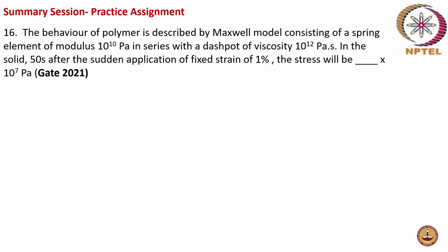Uh, stress will be constant when it's connected in series, so the strain will vary. They have said a fixed strain is applied. Now they are asking for the stress for the entire system, not just for the spring or just for the dashpot. Here the polymer is described by the Maxwell model.